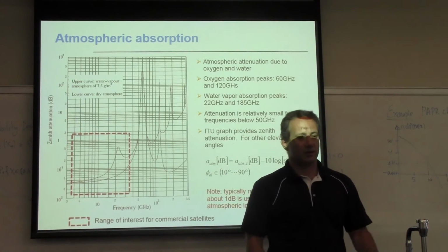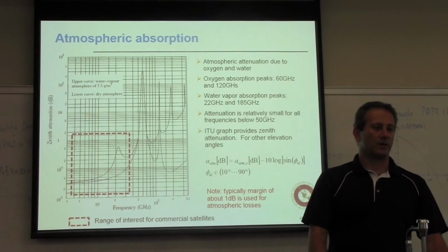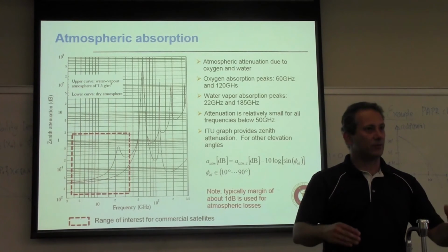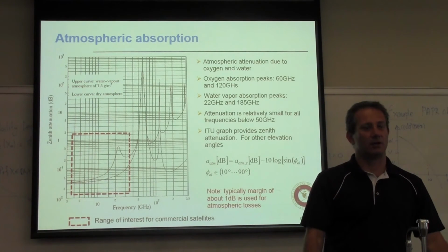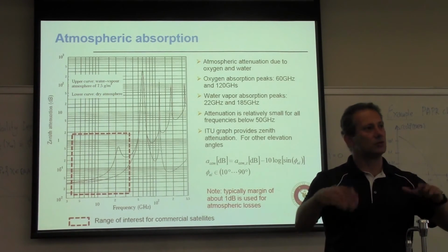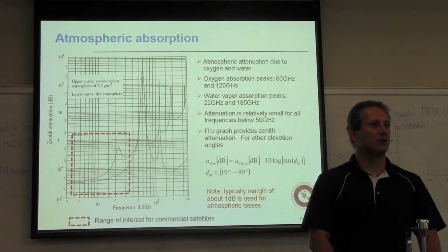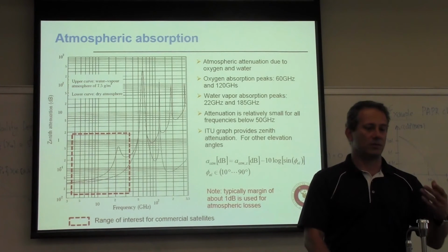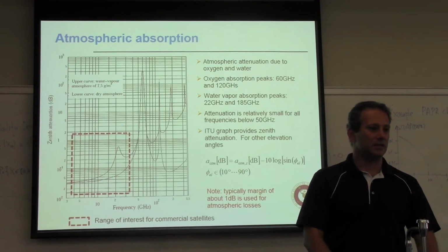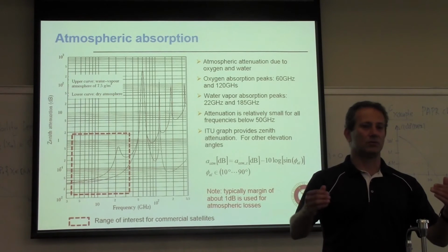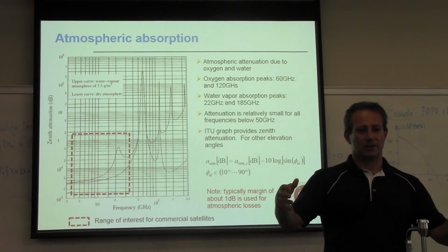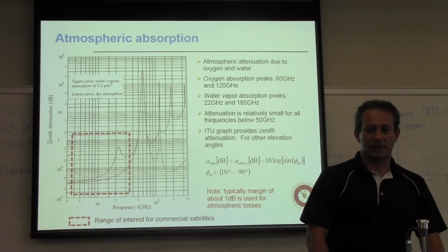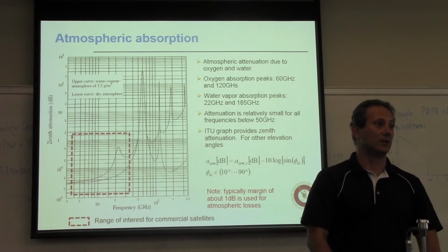And the absorption that you get, in this case from oxygen, is bad if you're trying to communicate over large distances. But if you're trying to reuse your spectrum over and over again over short distances, it actually helps you. And now you can buy 802.11 AD transmitters and receivers that allow you to communicate usually with electronic devices inside a room.